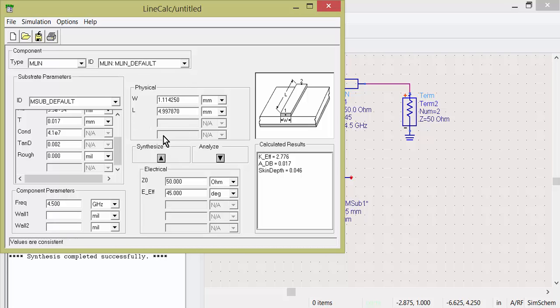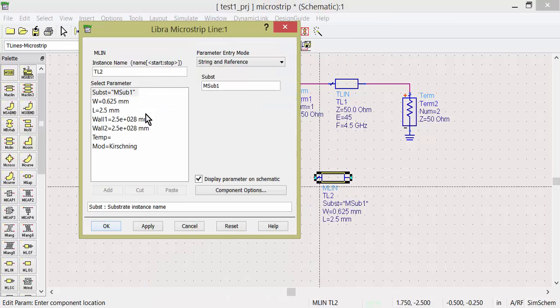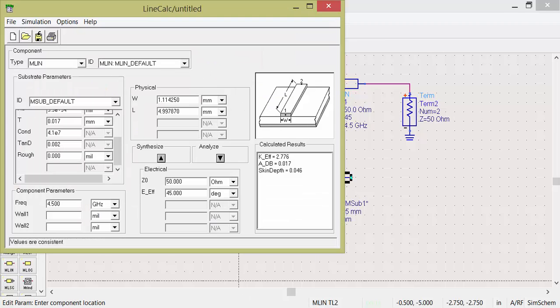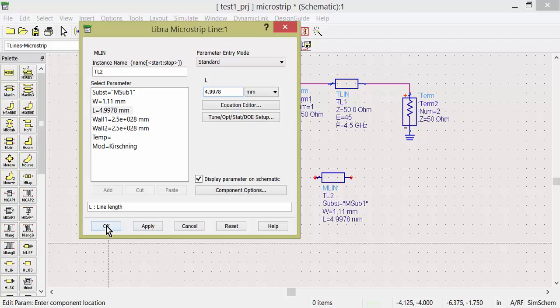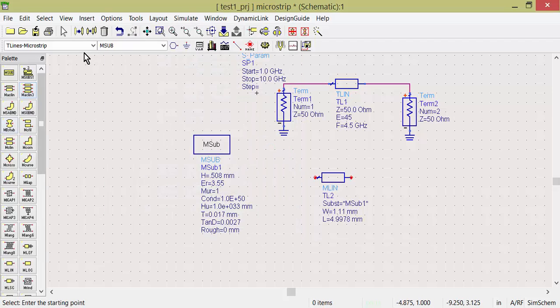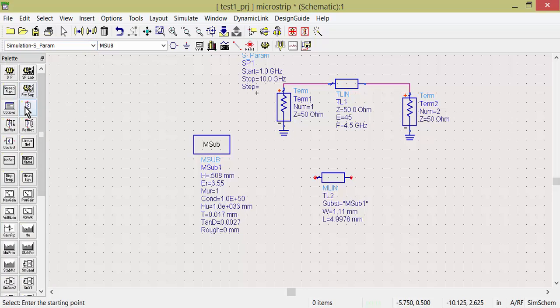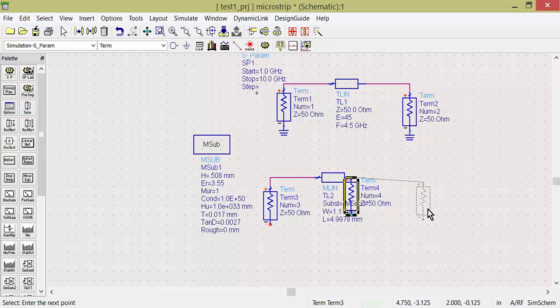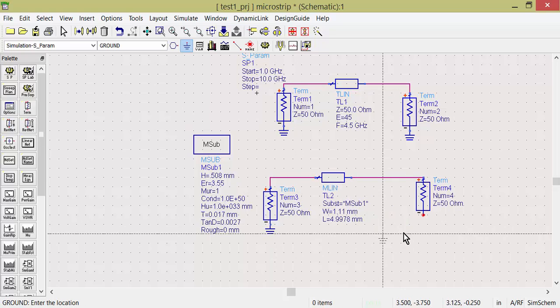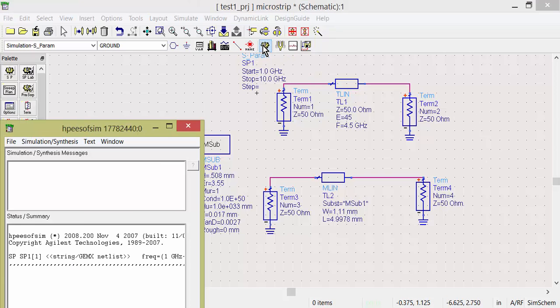Then I have to again reterminate, port 1, port 3 and 4. Here I am giving different ports so I can tally the results. The earlier result is equivalent to the theoretical model. So you can see two results I have shown, the earlier existing result and using the substrate, what the effect is. S33 and S43. See, there is so much deterioration coming, so it is not distinguishable here.